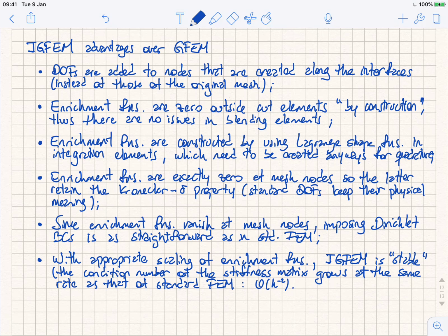So this is an important difference. Right now in the generalized finite element community, there is this main drive to search for stable generalized finite element methods. These are called SGFEM. The idea is that you basically have to choose enrichment functions that remain stable with the method, so that your condition number doesn't blow up when your discontinuities are, for example, approaching nodes of the original mesh. So there is ongoing research in this area, right?